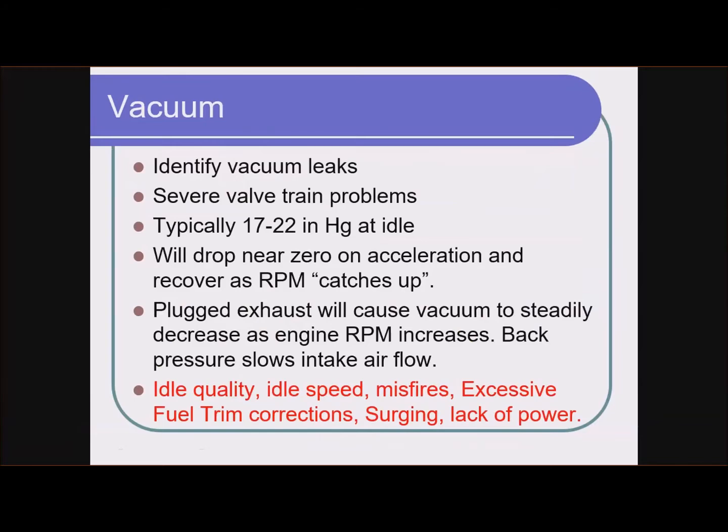On other vehicles, like if you take a carbureted vehicle and you create a vacuum leak, it's going to run very rough, nearly stall. And on a fuel-injected vehicle that uses mass airflow, a vacuum leak, depending on how big it is, can just cause fuel trim problems, or if it's big enough, it can cause very poor running. So I have a picture that I'll show you in a minute that can help kind of explain one thing that I ran into once.